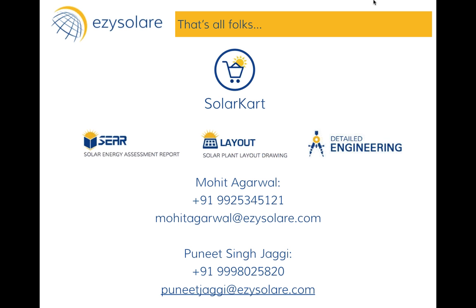It also depends at what place you are making the guarantee. If you are including the transmission losses as well, then probably 1 to 2% can be included in transmission losses also. So even though the contractor might be willing to give a PR guarantee of 78% or 76%, you might end up getting a guarantee of 74% because the transmission losses might contribute 2% as well.